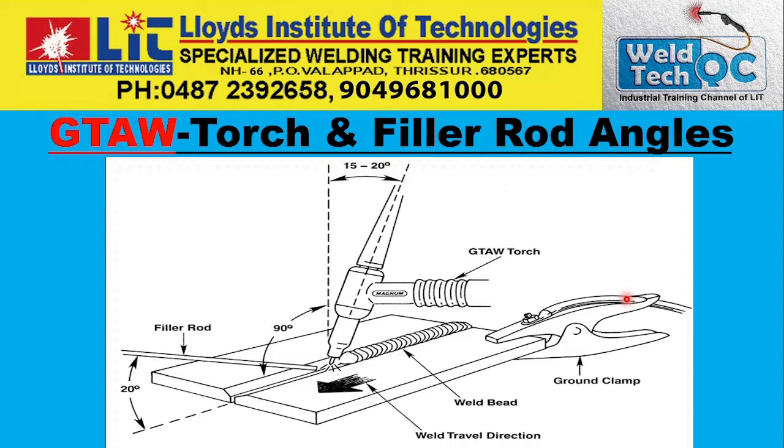This is the angles of the filler rod as well as the torch. From here around 15 to 20 degrees, that means from here it will be approximately 70 to 75 degrees. The torch is tilted, and similarly the filler rod you have to keep at an angle of about 15 to 20 degrees, so that here this angle forms a 90-degree angle. And you proceed accordingly.